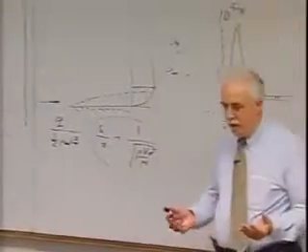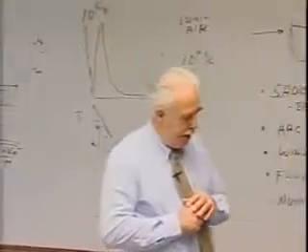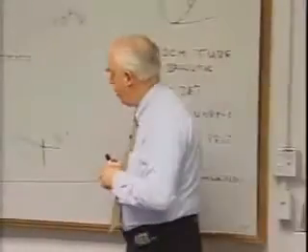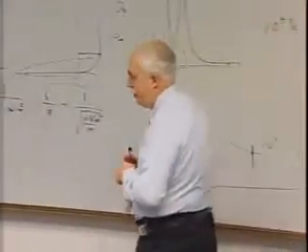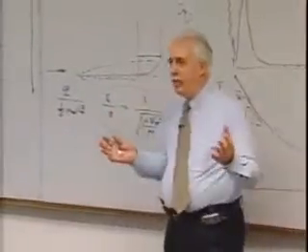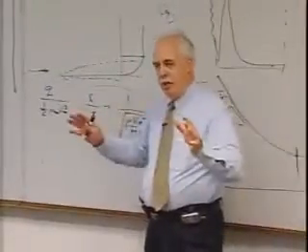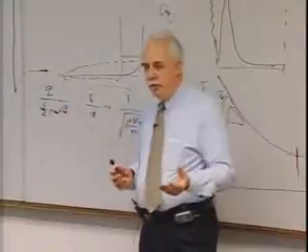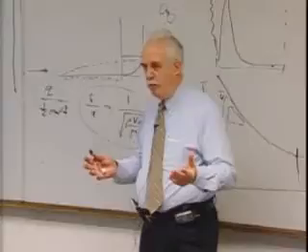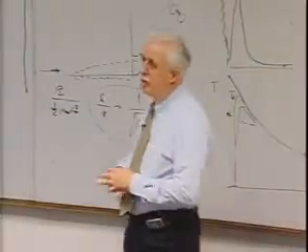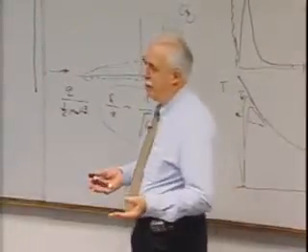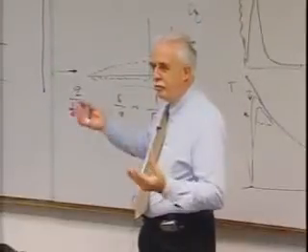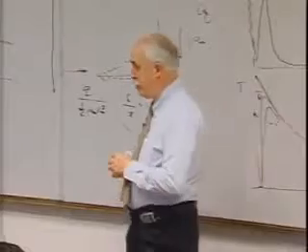I mentioned dissipating this energy. George Struhall was in charge of the thermal protection system on Apollo, and I used to come to him and say, wow, we take care of 98% of that energy by putting it into the air. We compress the air, heat the air. You only have 2% to deal with, small percentage. And he used to come right back to me and say, I do the same thing. I get rid of 98% of it, and only 2% gets to the structure. And in fact, that's true by design.